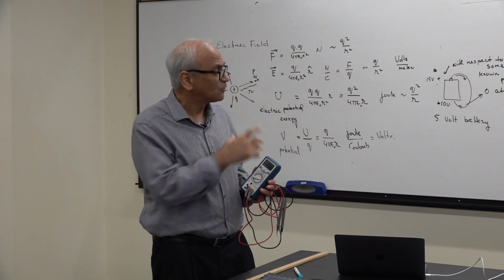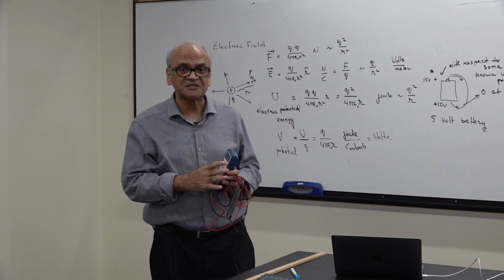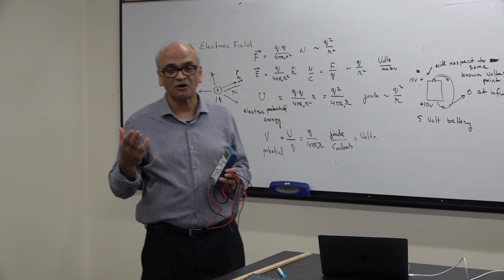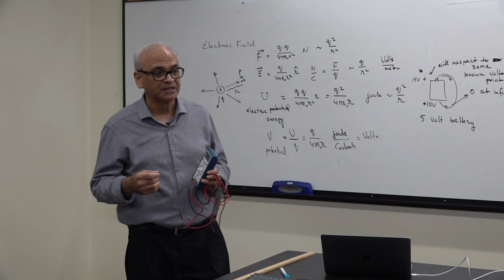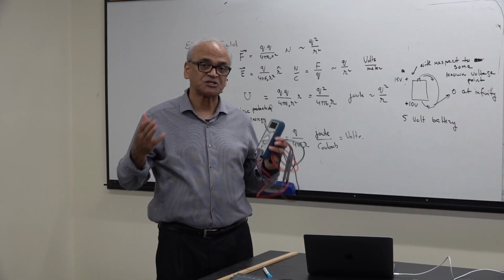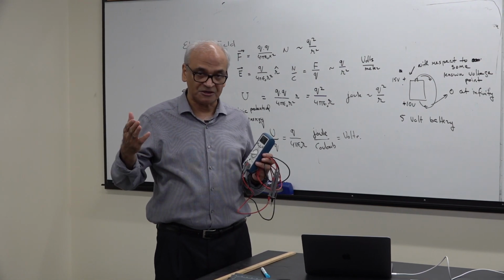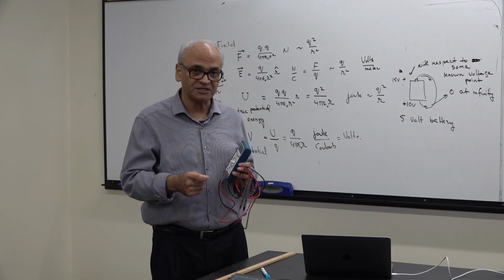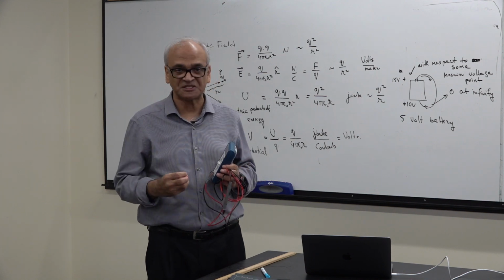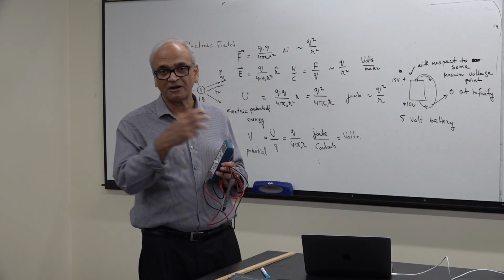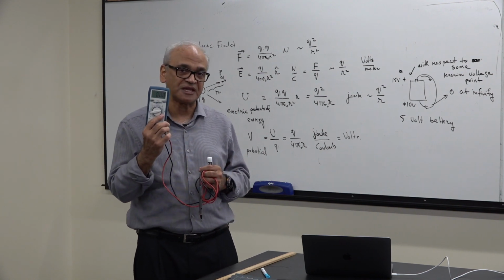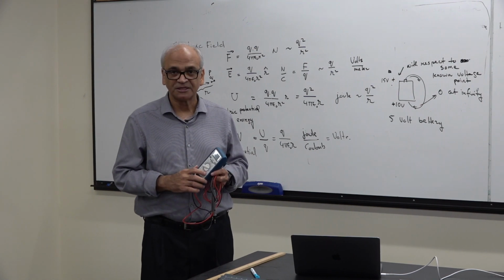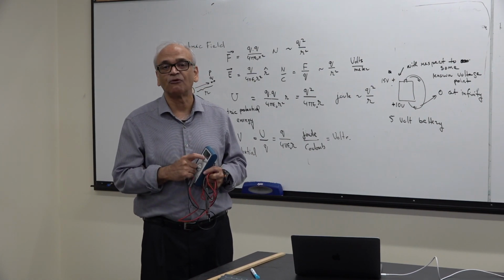So going back to it, the reason voltage is very easy to measure is Ohm's law. I'm not going to talk about Ohm's law right now. It's basically if you have a voltage difference between 2 points and there is a resistance when you connect those 2 points, then the current there is defined by voltage over the resistance. So the voltage is simply current times resistance. So there are resistors in this voltmeter, and by simply measuring current and multiplying by the resistance, you can get a voltage.